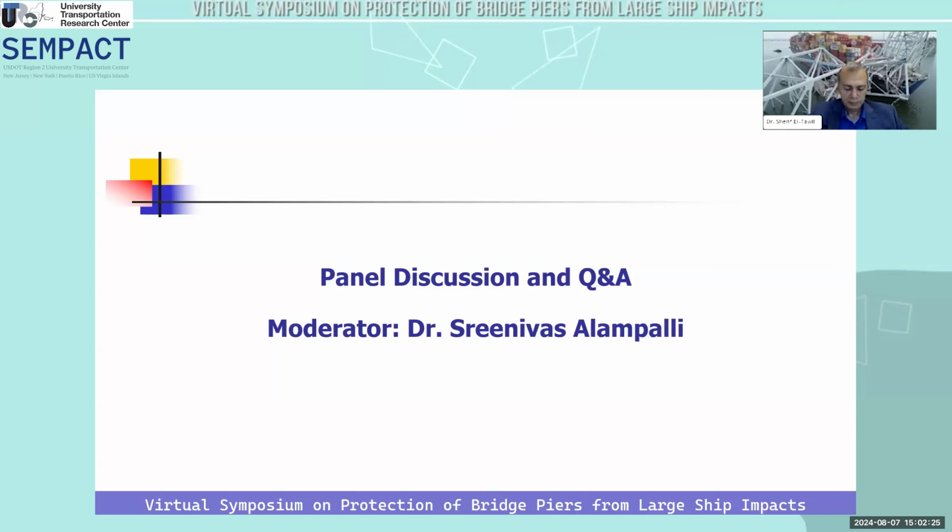And in the US, it seems we keep wanting to put our bridge piers close to a channel. If it's a 1,000-foot channel, we'll have a 1,500-foot main span. Well, then you've got to design those piers, in my opinion, not to withstand an impact, but you've got to put dolphins, islands, something to protect them from collision to begin with.